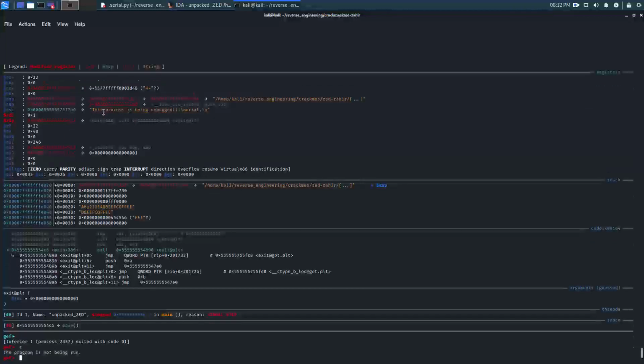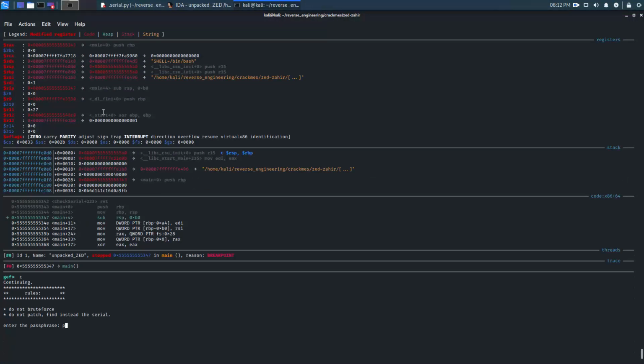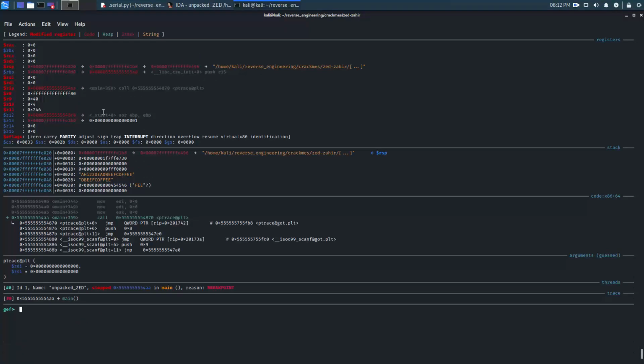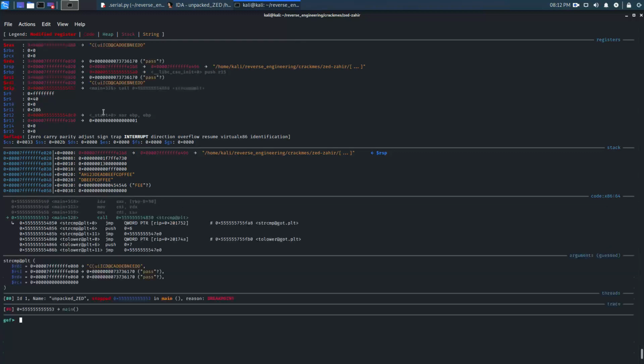So, like I said, there's a way we can get around this though. So let's go ahead and run this again. Continue, pass, and then let's see, hit next. And now, if you recall in one of my previous videos, you can actually set registers in here. So I'm going to set this to 0, and then I'm going to hit continue. And you see now we've gotten past it.